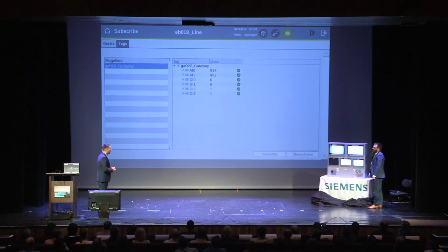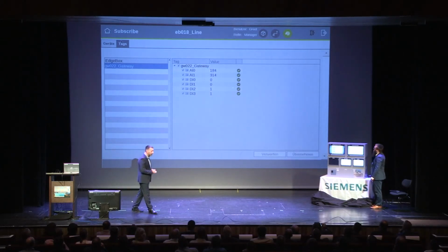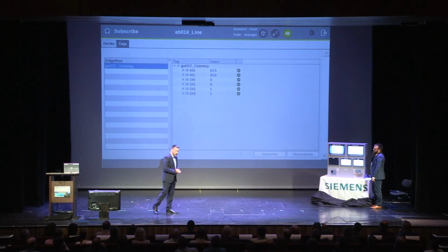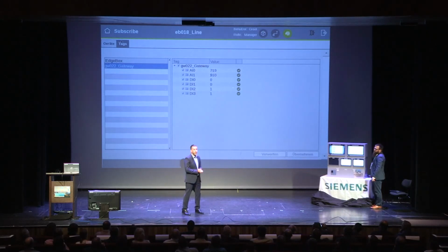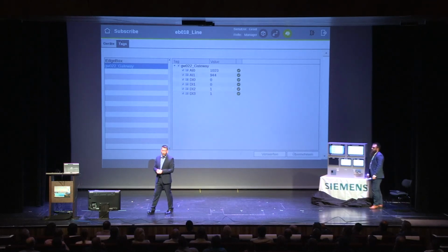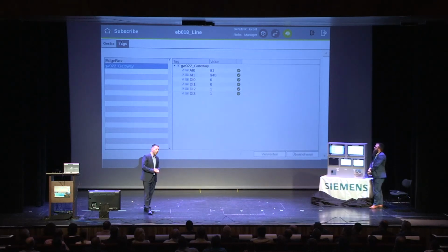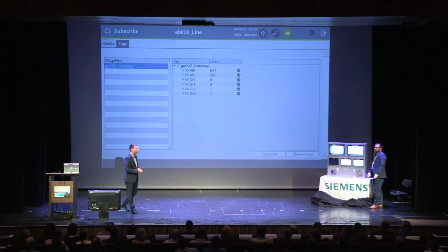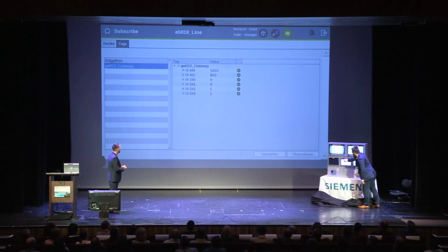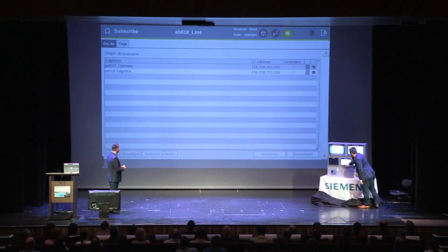For the sake of easiness, we also provided a kind of network scan, because we believe in an operator standing in front of his machine, and if he wants information from another machine, he should not need to know where this machine stands or what the IP address is. Therefore we implemented a rudimentary scan to look up other devices in the network.